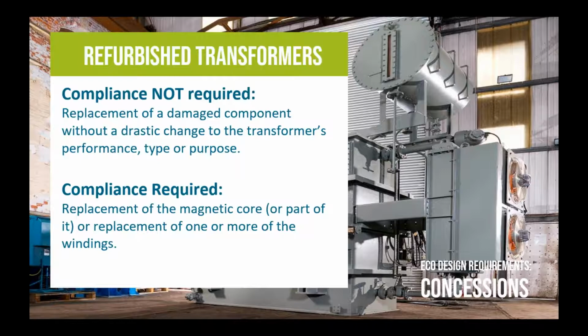But there is a case where the refurb transformers have to comply. This is if the refurb includes replacement of the magnetic core or part of it, or replacement of one or more of the windings.